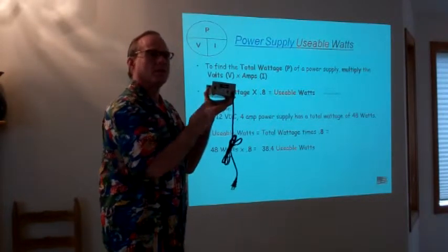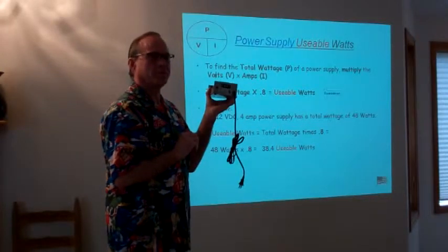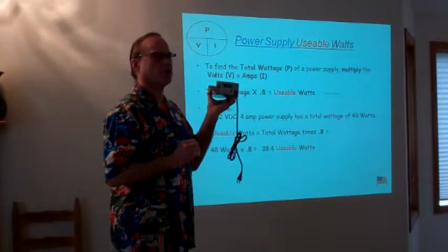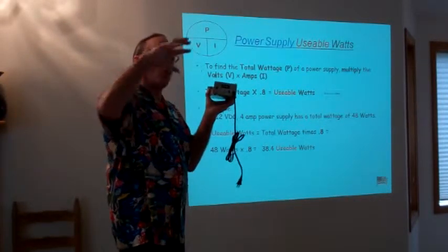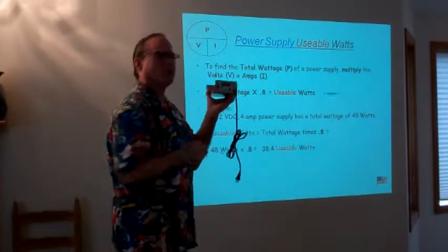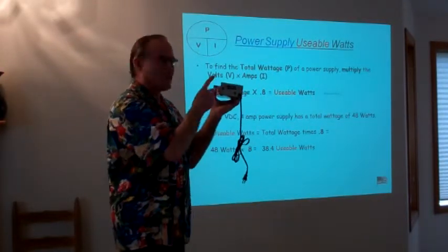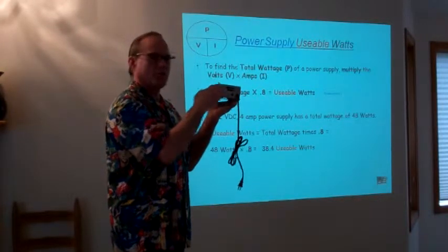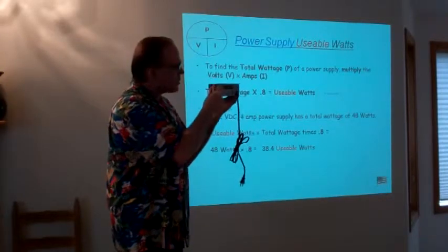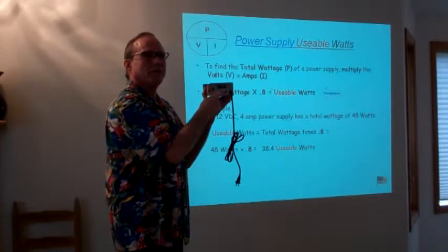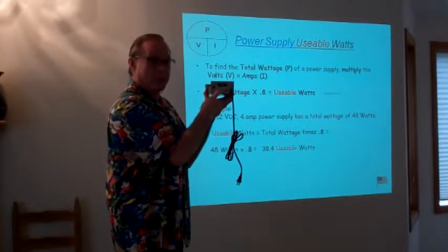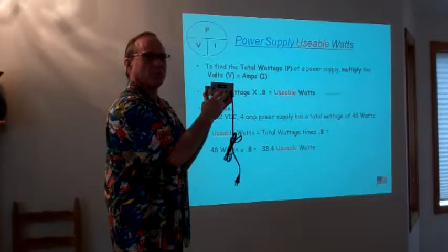Why do we need more? Because there is a surge. In all electrical circuits we have a surge when we are starting or applying our power initially, so we actually develop more current at that particular moment in time. This power supply has been engineered so that it will take that 40 watts without tripping the breaker or doing damage inside here, but to run continuously, it's only going to be pulling 1.75 amps at 13.8 volts, which is 24 watts continuous.